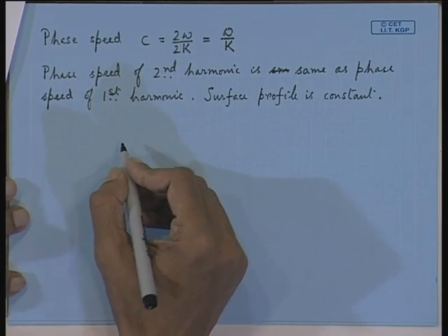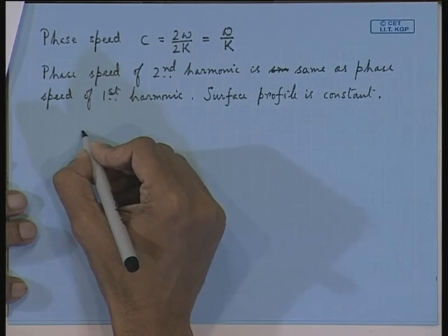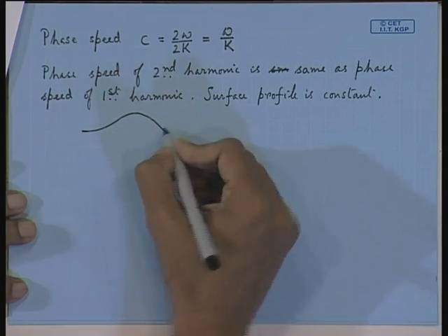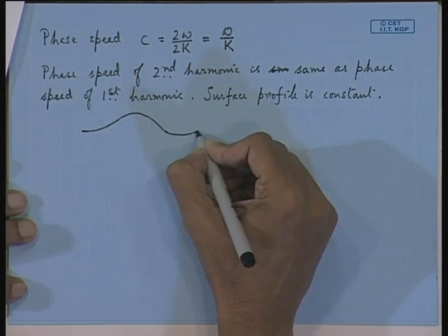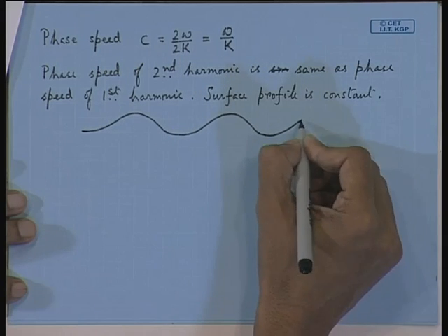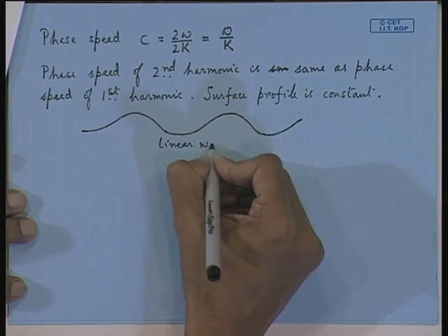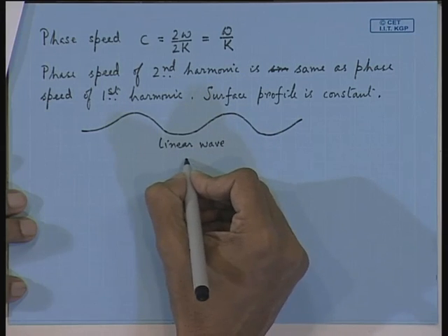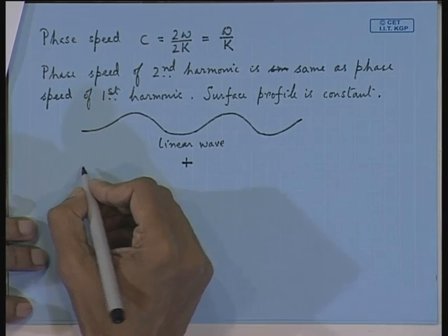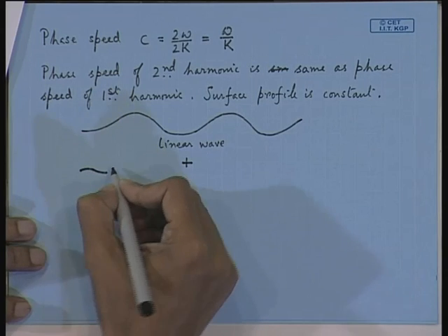So now we are getting two waves. So just you draw the linear wave, Stokes first order. So this is your linear wave profile. Now you add the surface elevation from second order or second harmonic. So second harmonic, you get smaller wavelengths, say something like this.